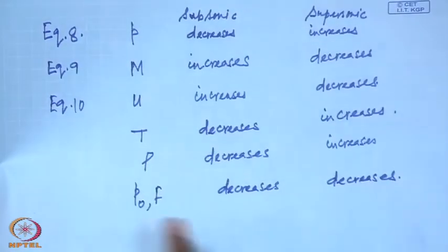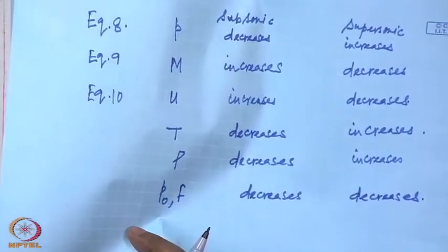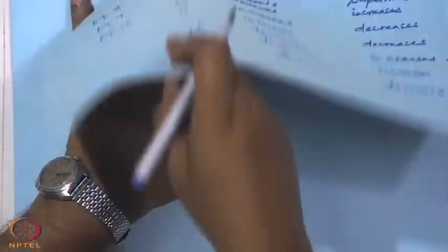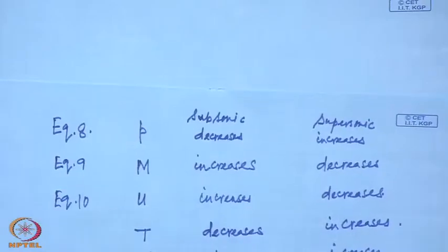So, this also suggests that Mach number in the flow due to friction always tends towards unity or sonic flow, and consequently the transition from one region to the other region is impossible.